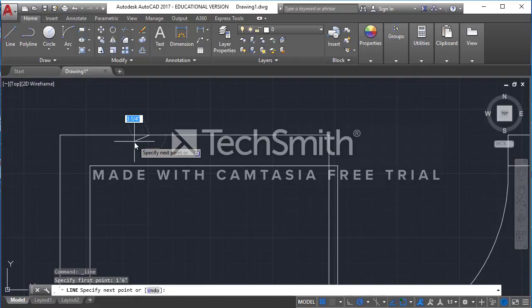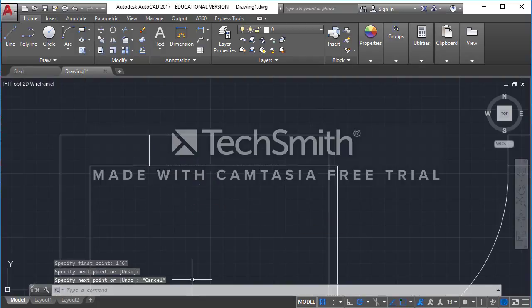As soon as you see that green line that shoots out across your screen, you can just type in the dimension that you want, and you will now be drawing your line from that point. So I now know that the start of my window is exactly 1 foot 6 inches from that corner. From there, I can just go down and connect my window.